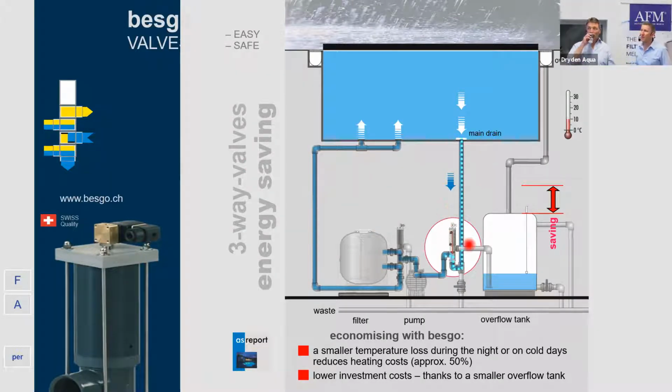Reason number 1: if we pull water from the bottom of a pool to backwash a filter, we're getting the cleanest water in the system to backwash the pool. The water that's pulling from the balance tank is actually the dirtiest that we have in the system. So a very good reason is to pull your backwash water from the bottom drain, because it's the cleanest that you can get. Wash your filter with the best water. Not so important, by the way, for AFM, but really important for sand.